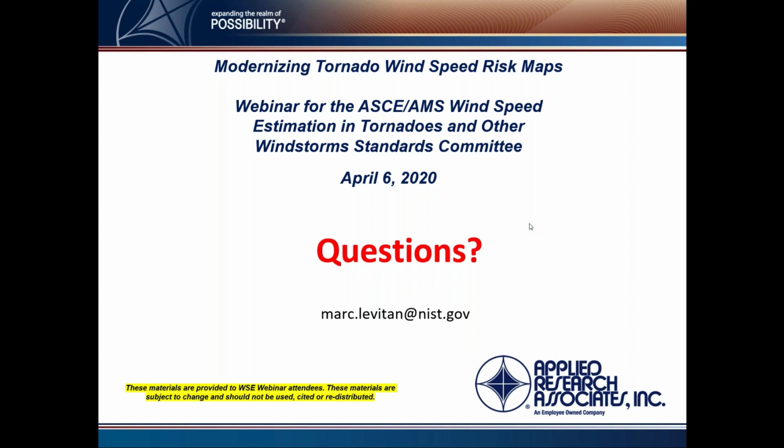we've only shown a few highlights. Like I said, even when we did a day-long version of this seminar, we couldn't get near everything from six years' worth of work. But yes, the model includes window breakage from debris, which is the single most important contribution to debris. There are other contributions, but that's the most important one. If it breaks the window, then you change the internal pressure in the building, and we've captured that.